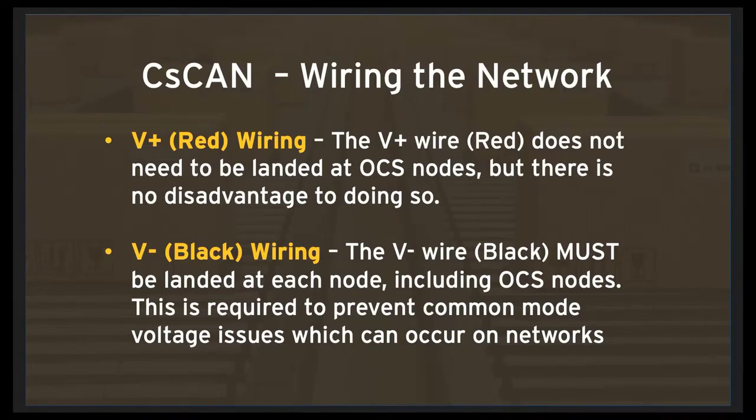All right, so just run V+ everywhere, connect it neatly so every node is wired the same, and then that'll be the easiest to deal with. But again, OCS nodes aren't going to actually draw any power from that pin. Now, what some customers will do is they'll use that same approach with V-, which is the black wire. That absolutely won't work. The V- wire must be landed at each node, whether it's an I/O block or an OCS, it doesn't matter. This lead is required to prevent common mode voltage issues, which certainly can occur on networks, especially longer networks.